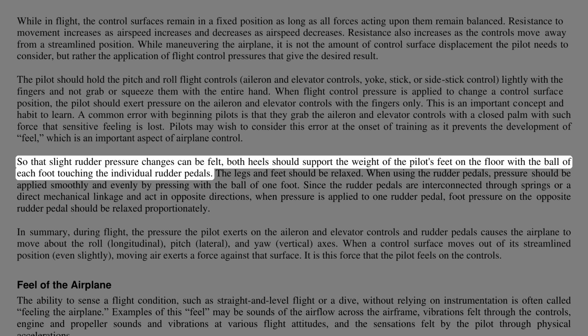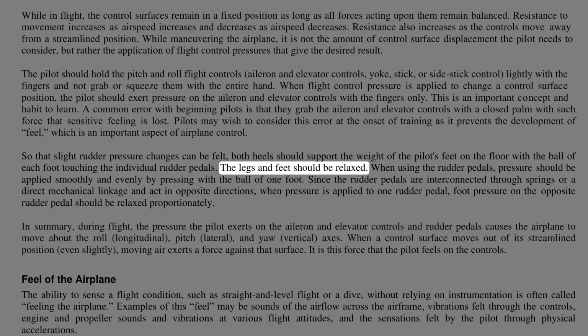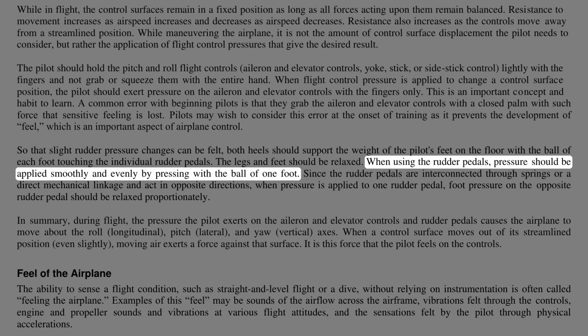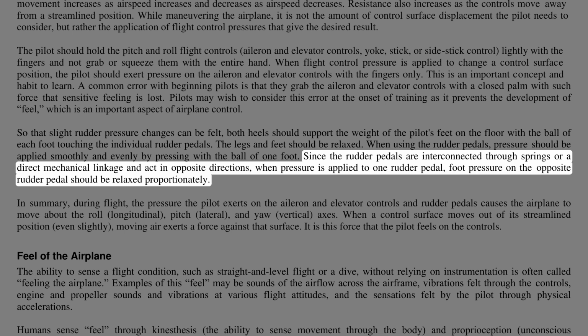So that slight rudder pressure changes can be felt, both heels should support the weight of the pilot's feet on the floor with the ball of each foot touching the individual rudder pedals. The legs and feet should be relaxed. When using the rudder pedals, pressure should be applied smoothly and evenly by pressing with the ball of one foot. Since the rudder pedals are interconnected through springs or a direct mechanical linkage and act in opposite directions, when pressure is applied to one rudder pedal, foot pressure on the opposite rudder pedal should be relaxed proportionately.